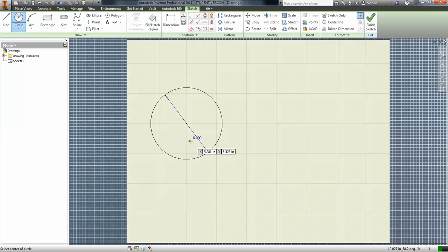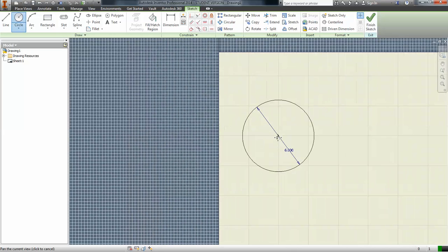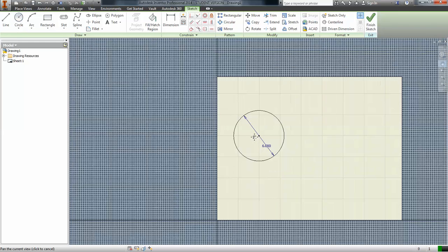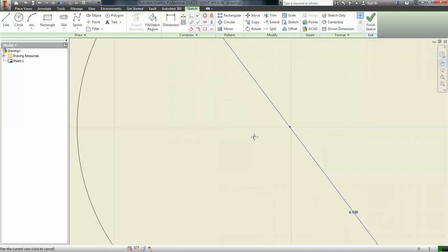And so I'm using my calipers right now. My axle is 0.125 of an inch, so I'm going to grab this and put it right in the middle, and then I'm going to scroll on my mouse. There's a little scroll wheel, and I'm going to go in. There's the center point. So I'm going to do another circle, and I'm going to click exactly the same point, and now this circle where my axle is going to go through, I'm going to make just a little bit bigger than the actual axle, so it's 0.125, so I'm going to make it 0.126, and I'm going to hit enter. Okay, so that's the hole that it's going to go through.